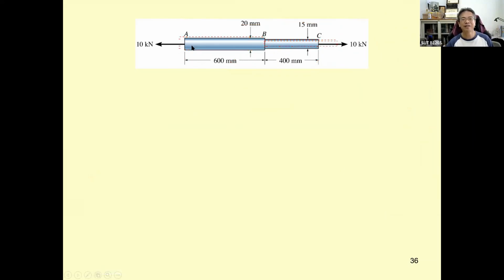Now you release the force. When you release the force, AB is going to return to its original length. But BC won't. BC will return some, and some won't. The part that returns, we call elastic recovery.